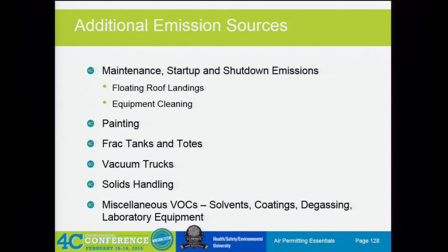Yep. Vapor recovery unit. You kind of indirectly mentioned it. Vapor recovery unit is going to operate very similar to your other combustion control devices, depending on how it's being used. Some vapor recovery units recover all of the vapor back into the process. Others will have a flare or something to control what streams don't get brought back into the process.